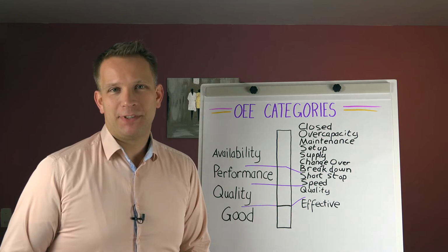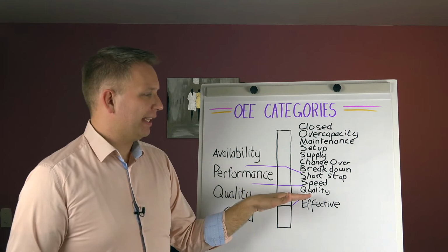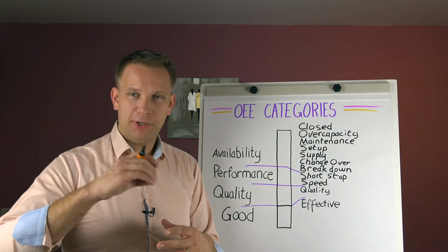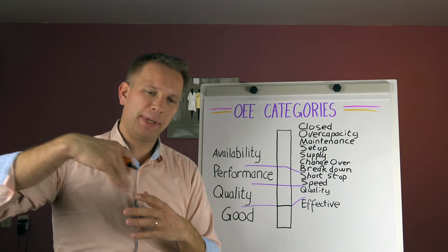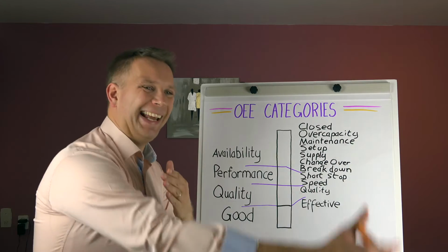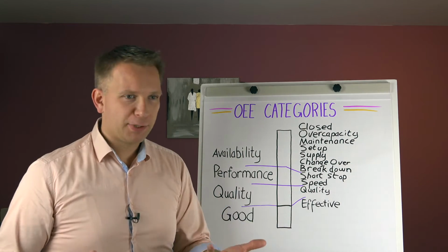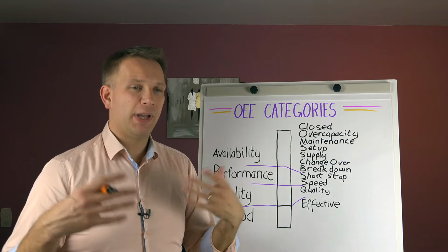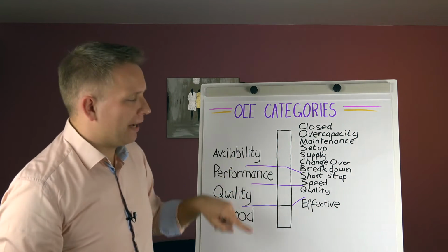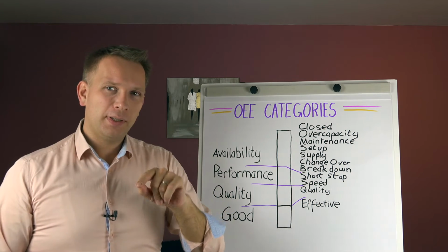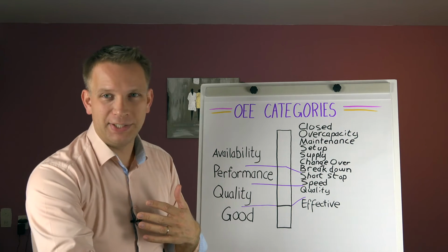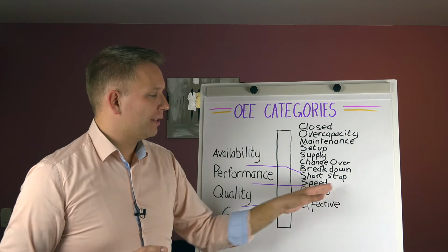It's difficult to measure. So the best way generally to do this is to have sort of a double counter on the line. So you have your heartbeat part of the machine, and especially if that's a bit in the middle of the machine, there you have your counter for the speed and all these things. But then completely at the end of the line, after maybe a couple of checks, maybe you have a check weigher tossing out some products, or you have visual control or things like that. So at the end of the line, sort of at the packing assembling stage, you have another counter, and that one checks if every product that came out of the heartbeat also made it till the end of the line. Then you have an easy way to check for quality.